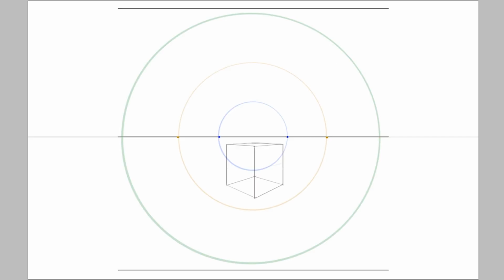The sphere has a slightly more involved construction that can sometimes be a little bit confusing to students. The first thing that we need to do is plot all our halfway points on each of the 3 axes. Here seen in 3 different colors: red for the z-axis, cyan for the x-axis, and magenta for the y-axis.